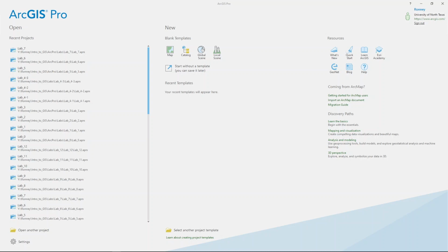The instruction says this is bad practice, but it is known to happen. Yes, and more often than it should. Usually from professionals without a GIS background. You'll get a lot of guys who use AutoCAD or something like that, and they'll send you a shapefile, and then they'll just say, "Here you go," and you're like, "No, I need to know what this was projected in first." In such cases, use the define projection tool to fix the problem. You usually have to get it from the person who created your shapefile.